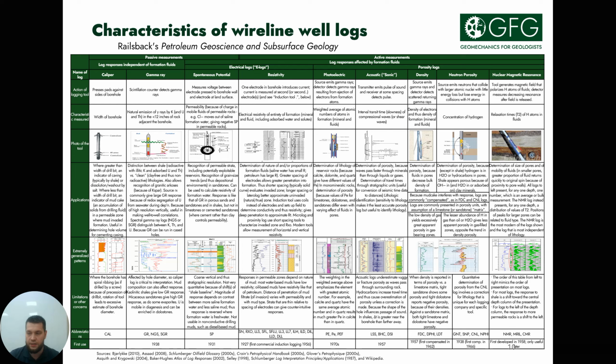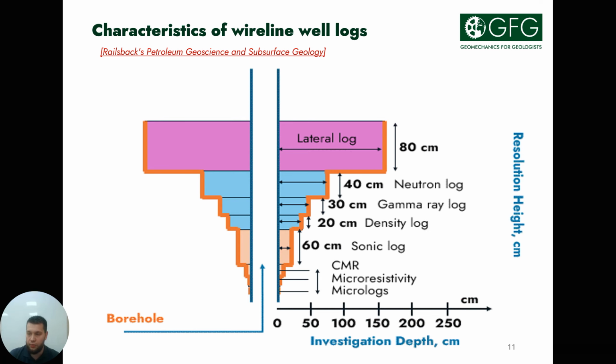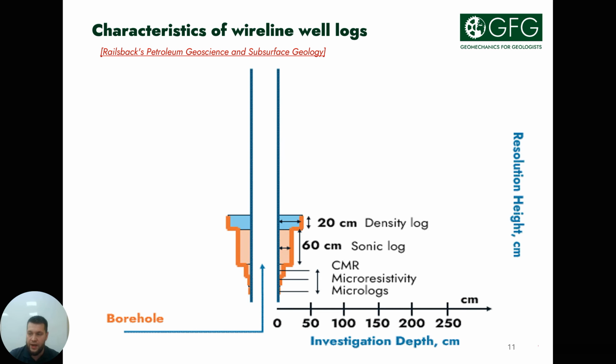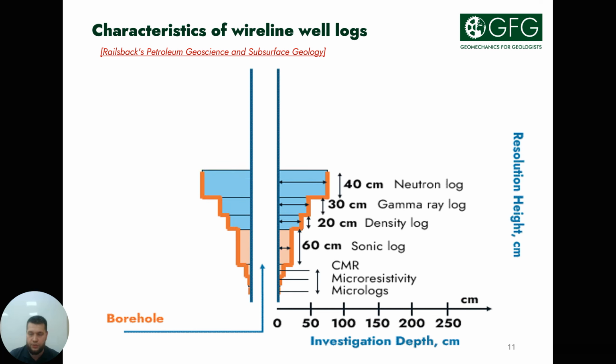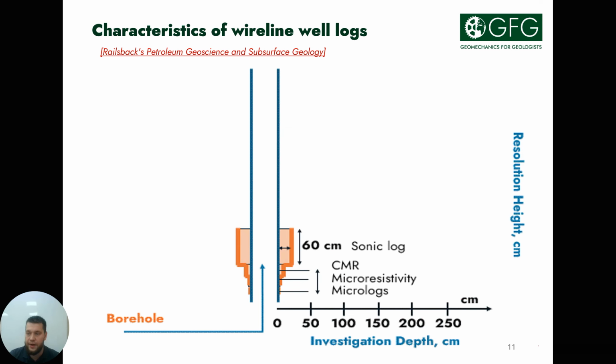Acoustic and resistivity methods can be used to calculate elastic and strength parameters as well as porosity and permeability. Microimager is used to assess rock bedding elements as well as the direction of breakouts and tensile failures in order to determine the direction of the maximum principal stress. It is important to note that each of the above methods is characterized by its vertical resolution and depth of research. Thus, electrical logging is characterized by the greatest depths.